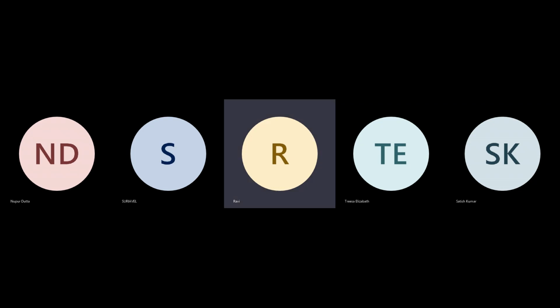So if it is in all the horizontal layers and all the vertical layers, then it's a different equation. Okay. So this is where it comes, whether it is horizontal congestion or vertical congestion. If it's vertical congestion, you have to look at modules like this. If it's horizontal congestion, you have to look at modules like this. If it's only one metal layer, then you look at how you push those routes to a higher metal layer, or from a higher metal layer to a lower metal layer. That's how you have to start analyzing whether I need to use route guide or I need to change my floor plan.